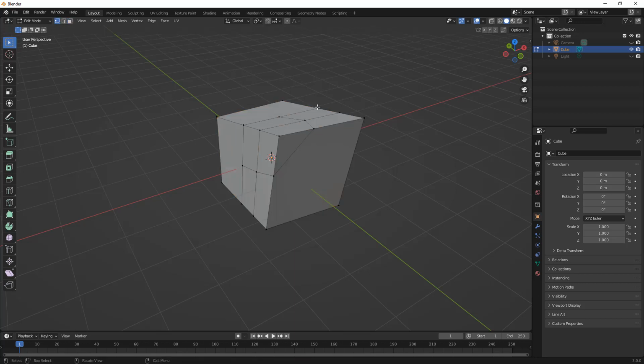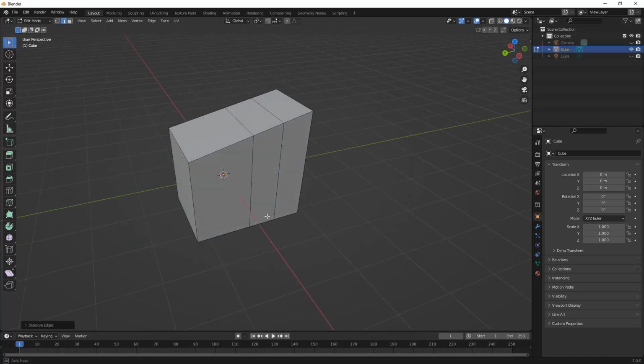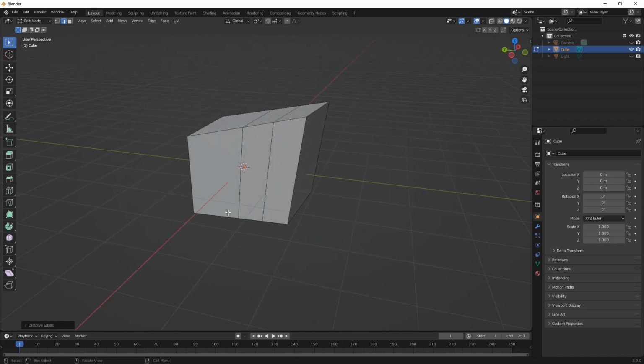Let's go ahead and try this with vertices. If I hold down Control and I select over here, you can see that it created the shortest path. This goes from this corner over to here. If I hold down Control still, I can carry on making those selections and again, very quickly and easily find and select those edges or vertices. Let's go ahead and select this edge, hold down Control, select this, go to Mesh, Delete, and Dissolve Edges. Now we're back to a more simplified version.